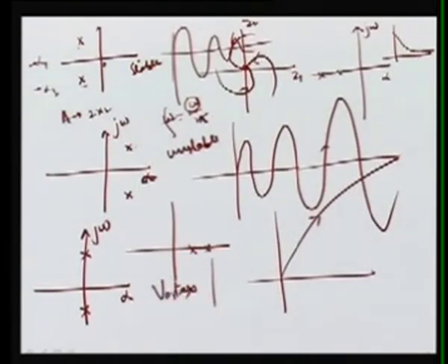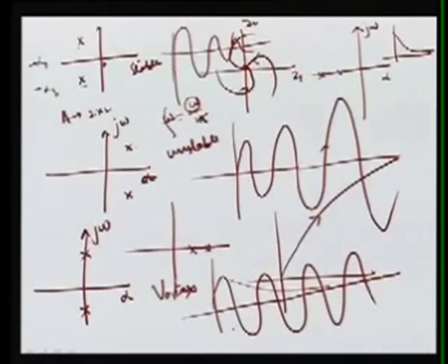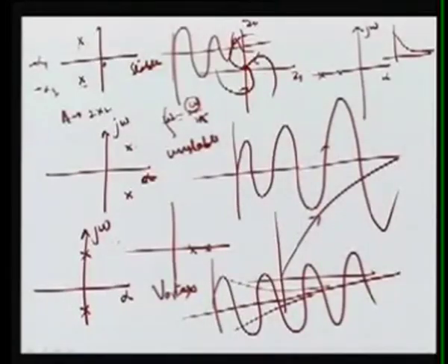Another is if your poles or roots are lying on the imaginary axis. This is your imaginary axis, and here is the real axis of the root. Then it will be a continuous oscillation, neither decaying nor rising. These things are also not required. In the power system, we want that it should decay and there should be some damping. Otherwise, if there is another small perturbation, the system will go out of step.